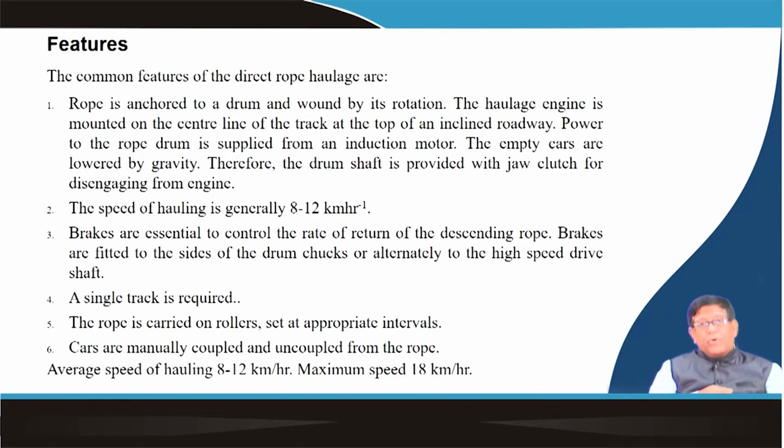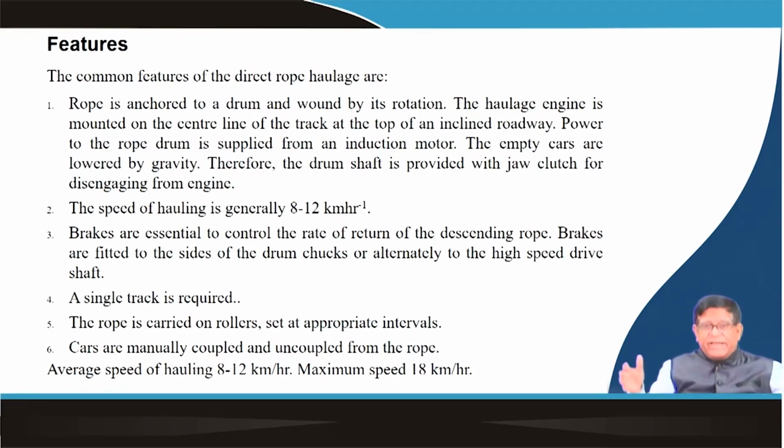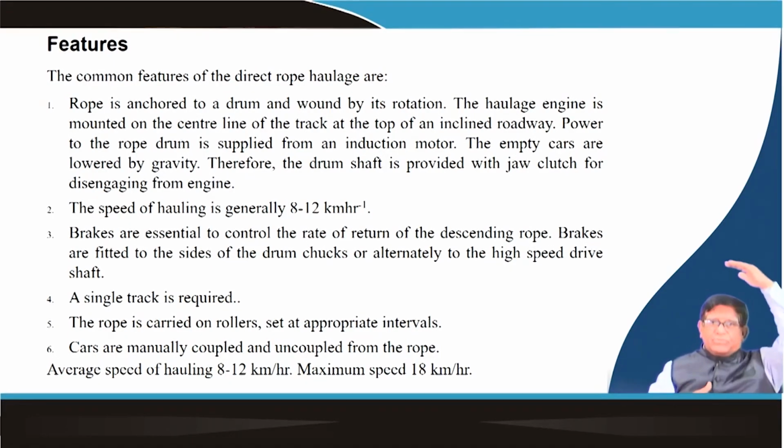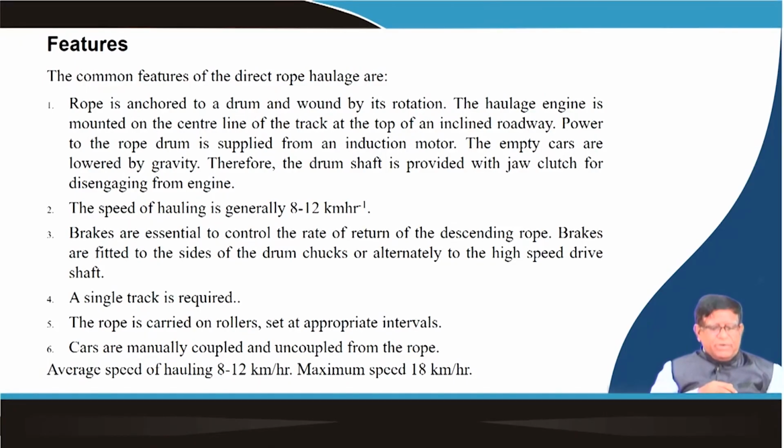Now, this is a very important thing, because in underground mining, haulage means how exactly you will excavate and then take the material out. If it is a wider road, that means you will have to excavate more material to take it out, and whether it will be able to support the roof and all, there is a condition. So, a lot of geotechnical and safety conditions will have to be looked into.